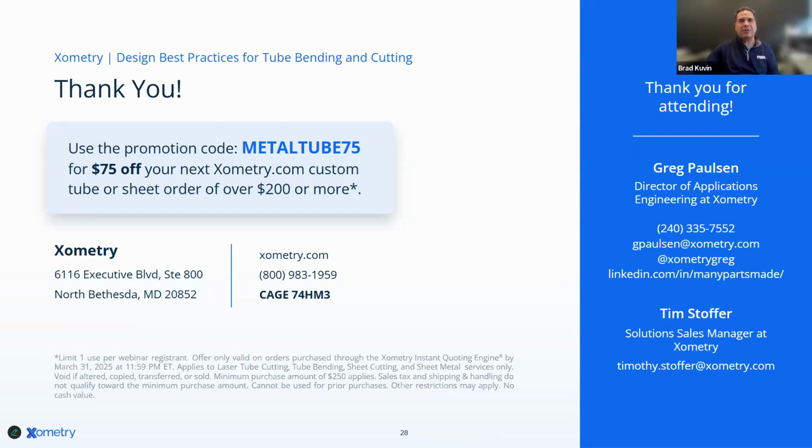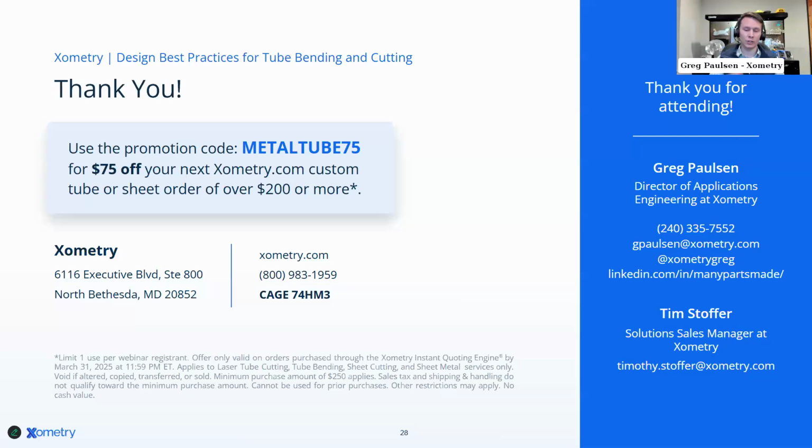Okay. This one on bending multiple radii in the same tube. I'm assuming that's a thing too, right? Yeah, we can certainly do it. It's just, you know, there's costs associated with it. And you'll see that. So if you upload your tube design and you have a different centerline radius, you're going to see that DFM feedback on the analysis. What may happen is you may get an ask, or our DFM engineers on post sale are going to be reviewing your design, your drawing, and we may raise a hand to ask a question saying, hey, just want to clarify your needs here.